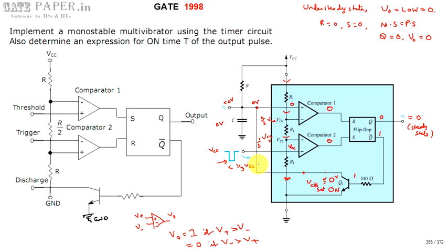That on condition makes capacitor voltage 0. So that again R will be 0, S will be 0. This cycle repeats and it will be in the same state as low level. That's why it is called a stable state. Once it enters into low level, at that time it won't change until a trigger pulse is applied.